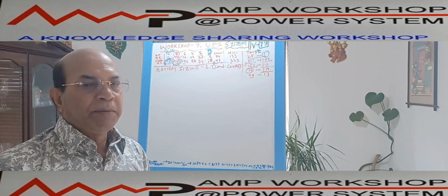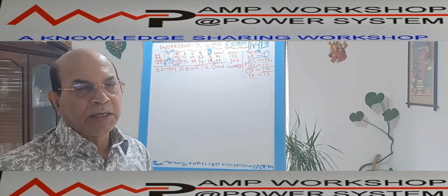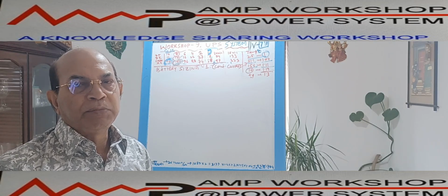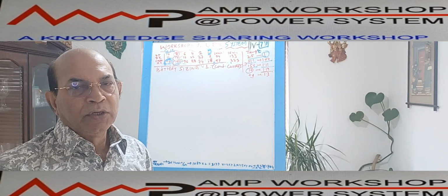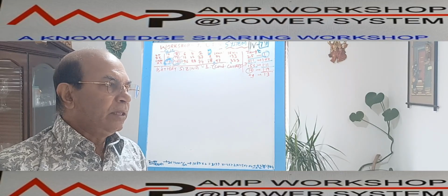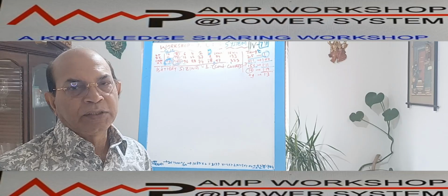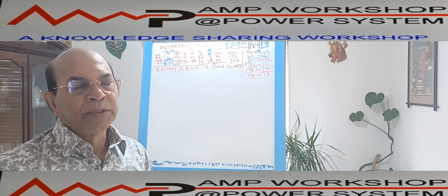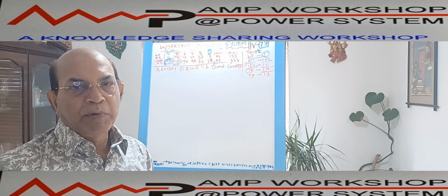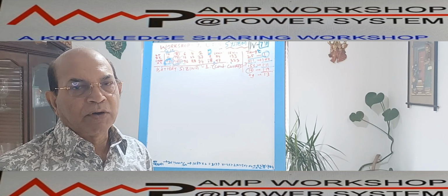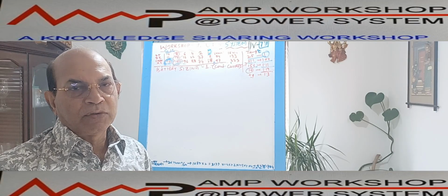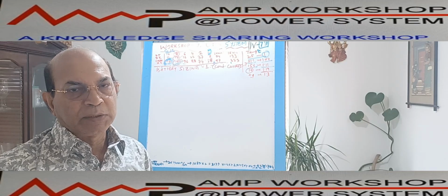In the case of the open type battery, the battery produces hydrogen, which escapes by evaporation, so water must be added regularly to maintain the specific gravity of the electrolyte. But in the lead acid sealed type battery, we do not add water regularly, because the oxygen produced at the positive plate combines with hydrogen to produce water, and that water is absorbed by the electrolyte. So the electrolyte maintains a constant specific gravity.